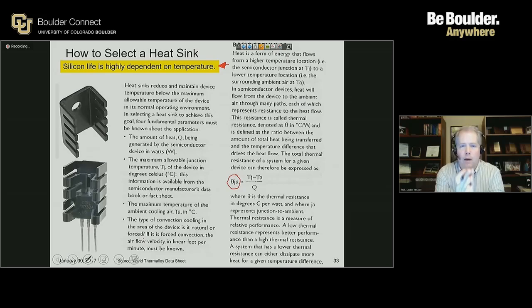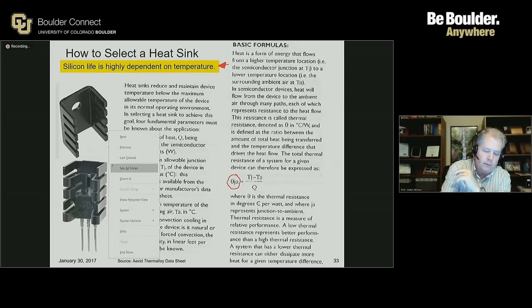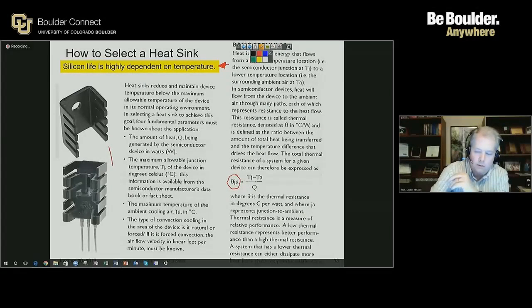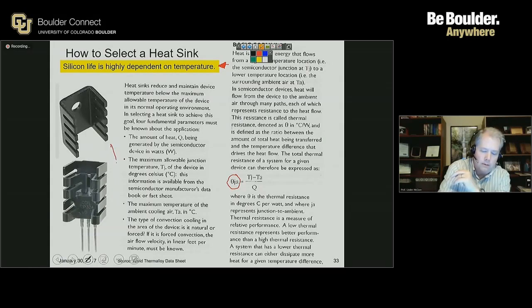But what I'll point out to you is that just because it looks like I've got a heatsink on there does not mean it's working efficiently. And what you should be aware of is that at that interface between the regulator and the heatsink, there are actually all these different little teeny microvoids.